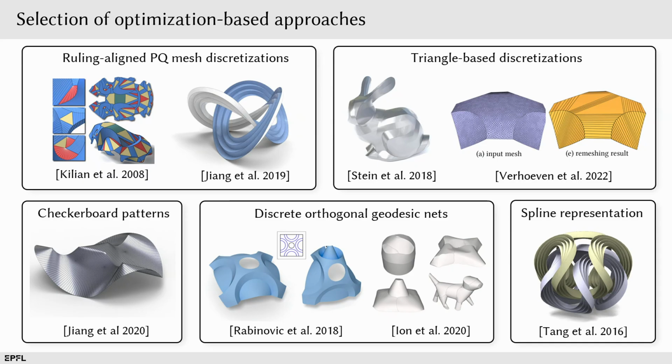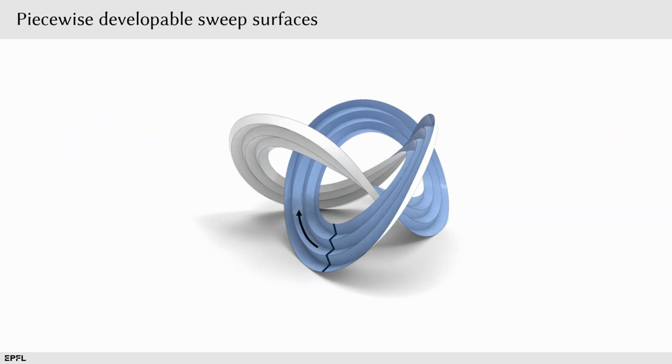So we were looking at developable surface discretizations that use planar quad meshes. In particular, when the developable patches have a regular arrangement, like in these split structures, it is natural to think about the strips as being generated by a polyline, so a set of rulings, swept and deformed in space.